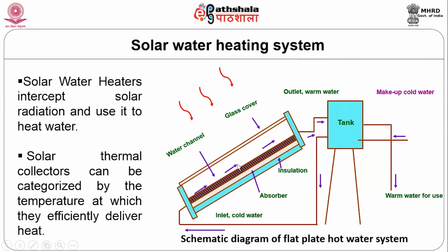and it is coming inside, and the water is flowing through the water channel, and the water gets heated up, and it goes up and reaches the tank. You may be wondering how the water is going from the bottom to the top without any pump. This is the thermosiphon effect: without any pump, the water is traveling from bottom to the